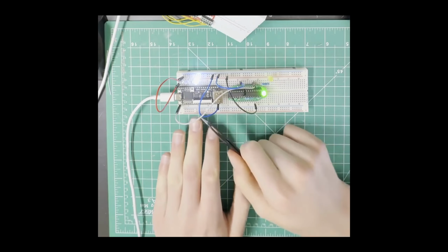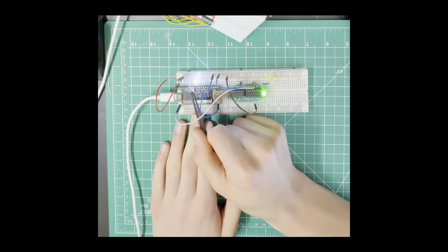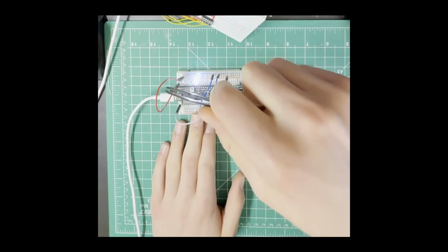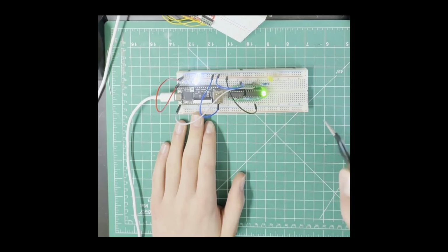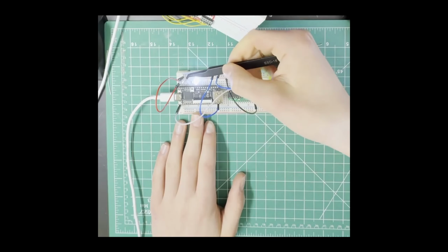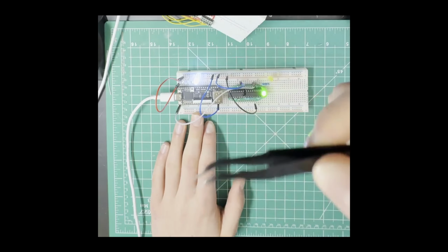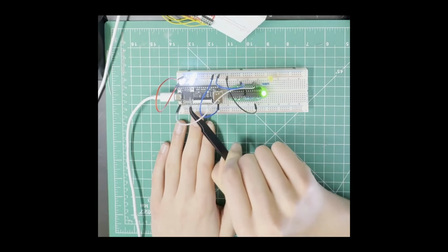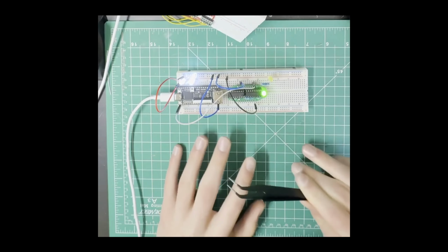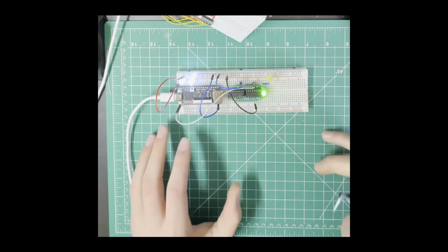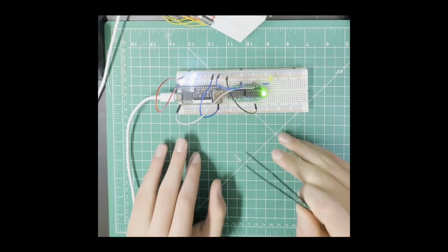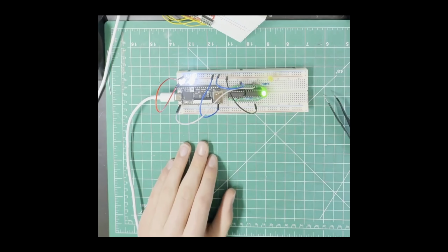And so you can see it's counting here. I think this is only outputting every 2. So I think I saw 1, 3, 8. And so it's really 1, 2, 3, 5, 8, and then 13. But as you can see here, I'm only outputting every 2. So, yeah, there we go. Okay, so this is the FPGA version. I'm going to go over to the computer now. I'm going to show you guys how the Verilog program actually works and have it running. See you guys there.